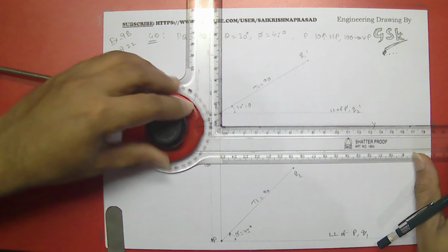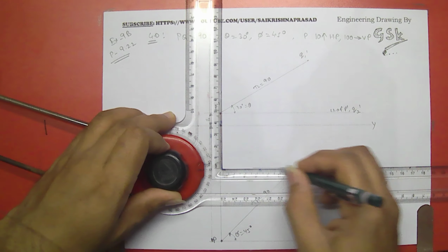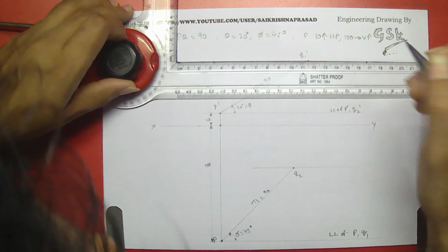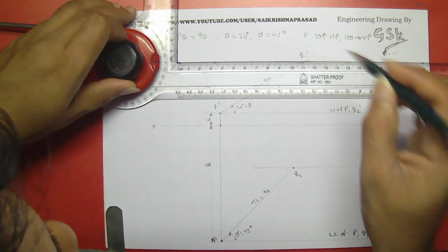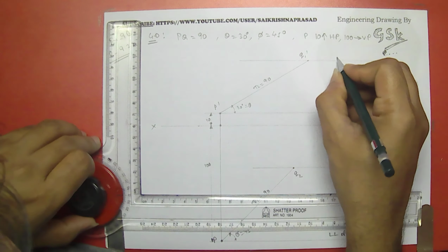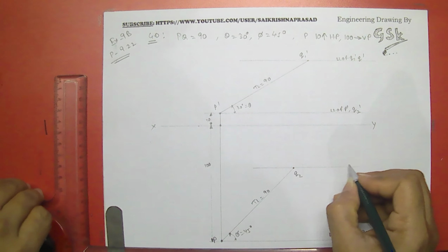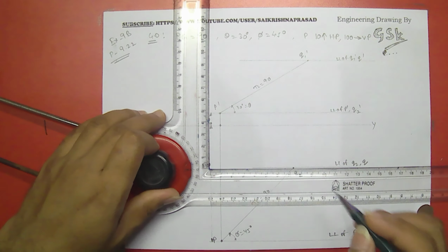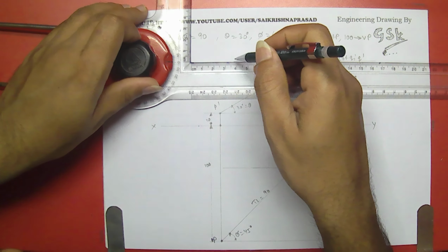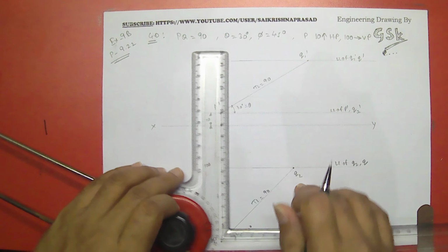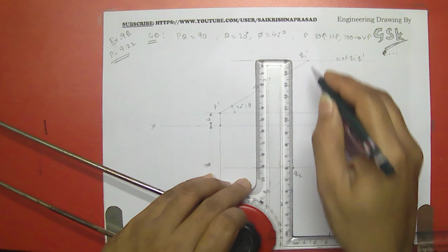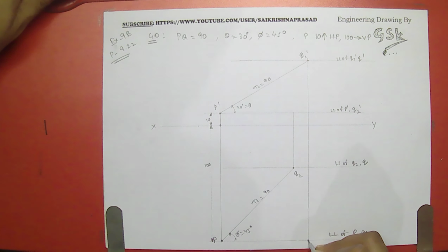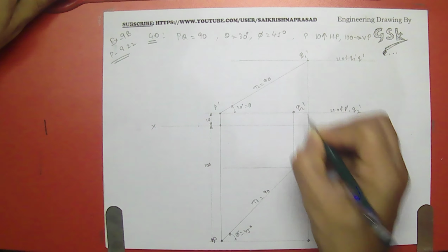So here let me draw the locus line for this one. This is LL of Q1 dash and Q dash, and this becomes LL of Q2 and Q. On this line I'll be getting Q, right? Next, I have to project this Q2 for the opposite, and this for opposite. Okay, this is Q2 dash and this is Q1.